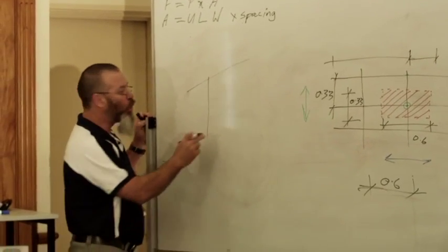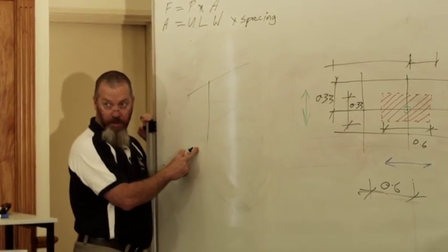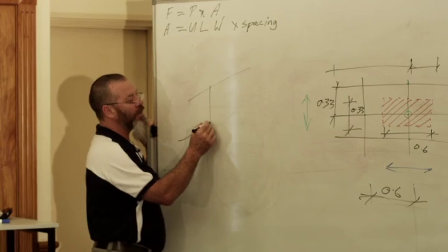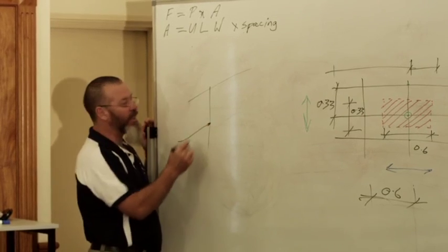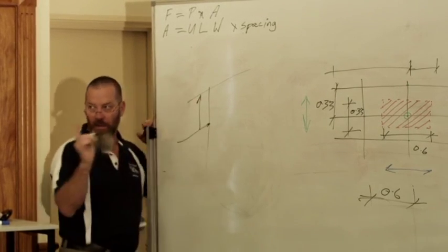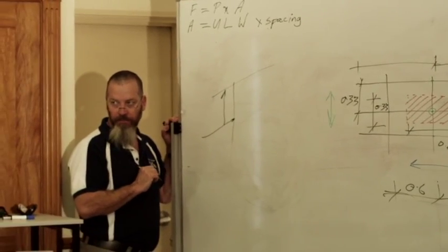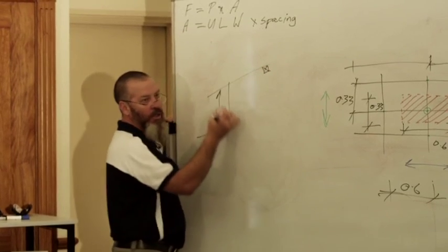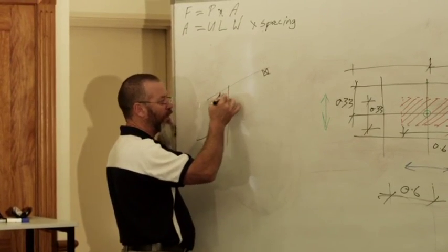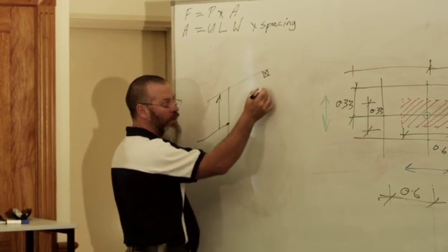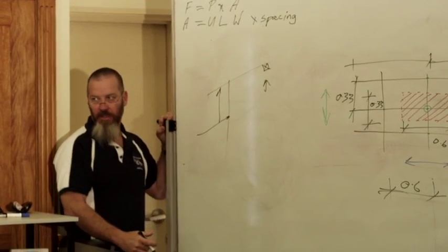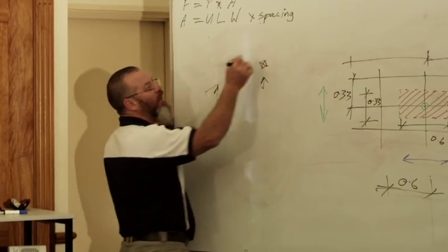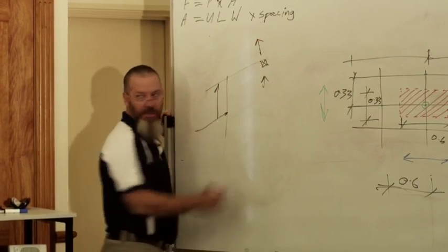Here's my wall frame. We're talking about uplift at this point. So wind can get to there, but it can't get any further than there. It can go up, and it only acts on one side of that connection. For all these other connections, let's say we're talking about an uplift connection, you can't get an underpurlin connection. Because of this wall, no wind can get at this connection from underneath. It's only going to happen where you get this suction force from the top of that connection.